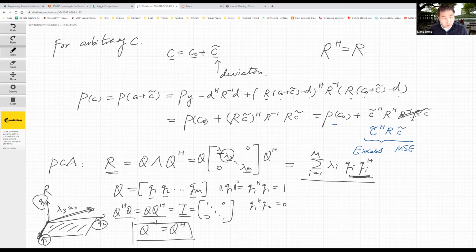That is indeed what we call principal component analysis, where this principal comes from. That's according to your principal eigenvalues. I need only talk about a few dominant or principal eigenvalues, because those are the subspace of the signal space that contain most of the energy.